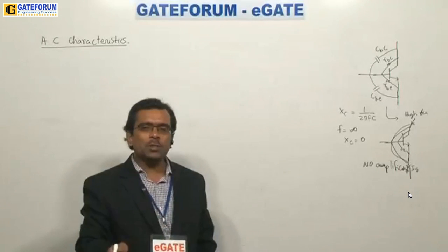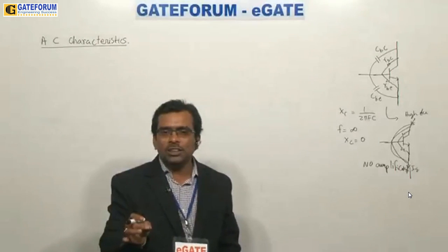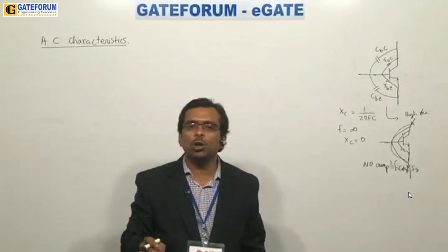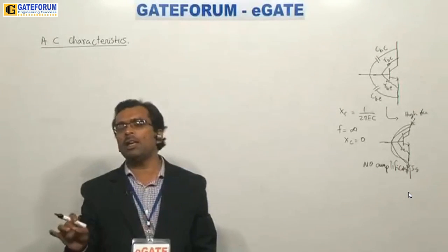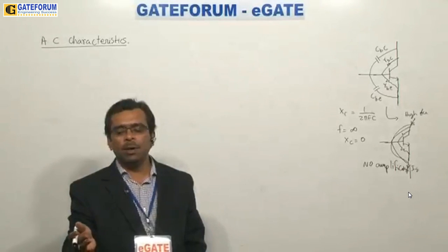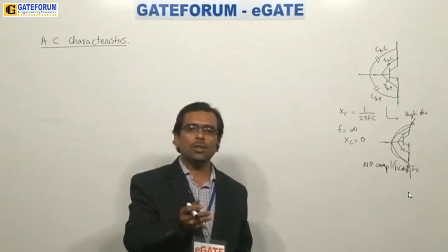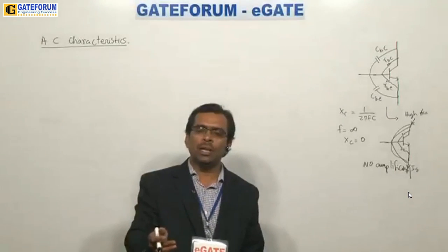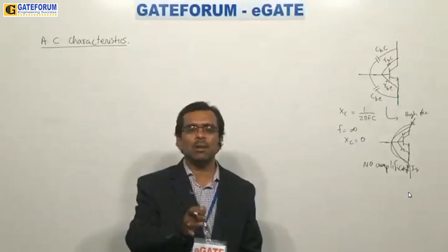So both areas have low resistance, and the transistor acts as a short circuit. The DC conditions show that the transistor is in active region, but it will not provide you any amplification, it provides zero gain. Why? Because whatever you give, the same thing will appear at the output. Now the transfer function, if you write V0 by Vi for AC, you will get 1, no amplification. As it is, the signal will appear.